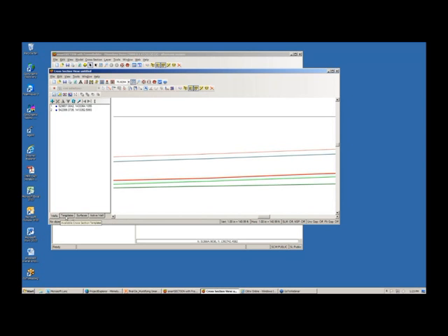They are the Wells, Templates, Surfaces, and Active Well tab, and each tab has its own use when making cross-sections. Let's start with the Wells tab here. It basically is going to list the wells that are in the cross-section and or the location points, either in lat long or XY, used to select our projected line of section. The blue dots or the circles denote these location points. If wells were loaded into the cross-section, we would see a list of unique well IDs here.